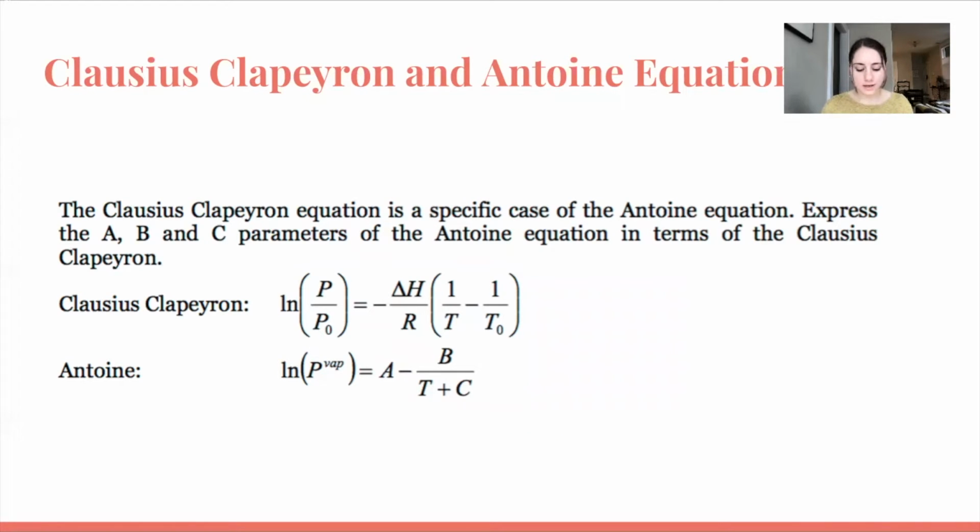and justify theoretically. Chemical engineers sometimes need more reliable vapor pressure estimates, and the Antoine equation is a simple 3-parameter fit to experimental vapor pressures measured over a restricted temperature range. You can see the equation here, where A, B, and C are Antoine coefficients. These vary from substance to substance. They also have separate sets of Antoine coefficients, as do components in mixtures. The Antoine equation is accurate to a few percent for most volatile substances.